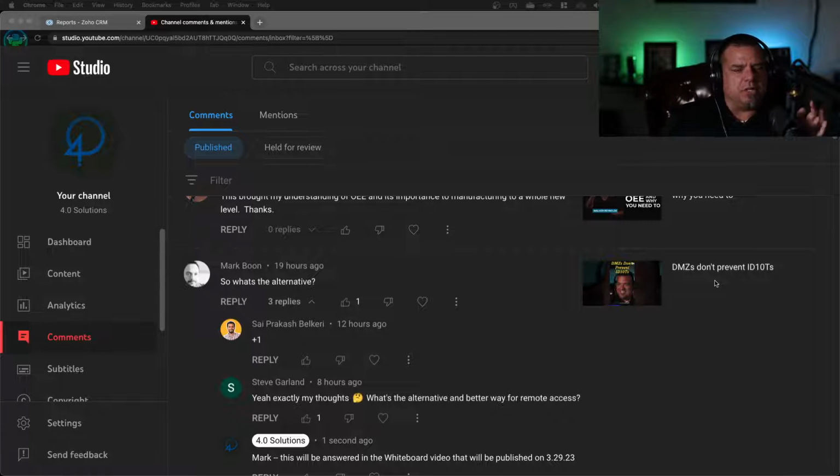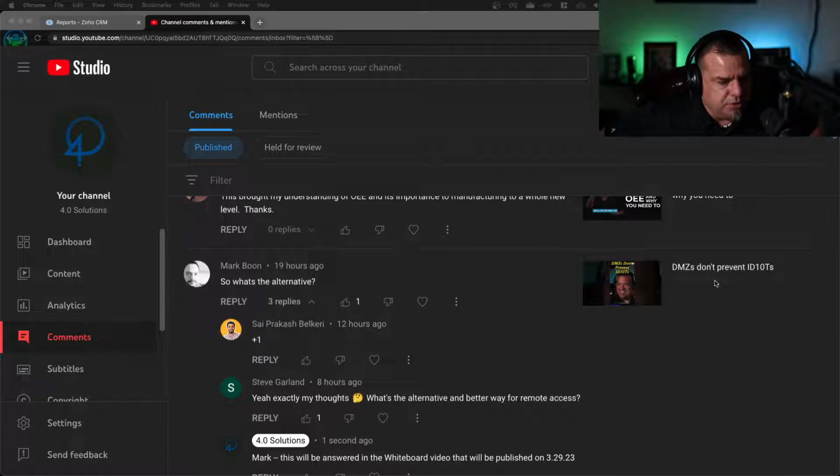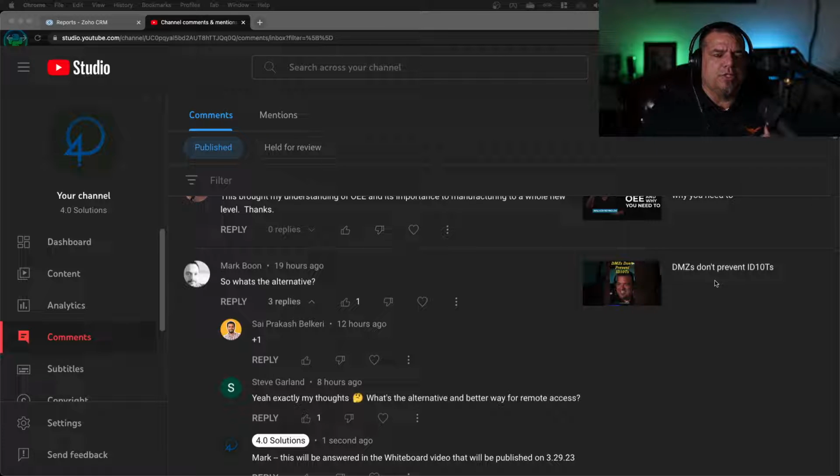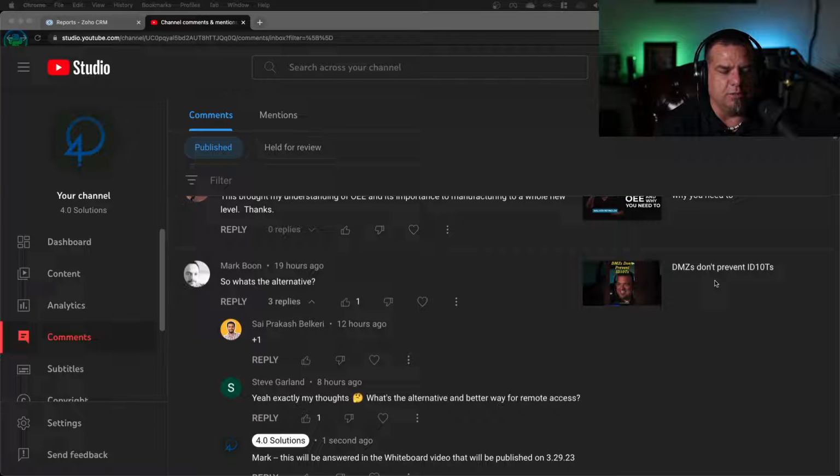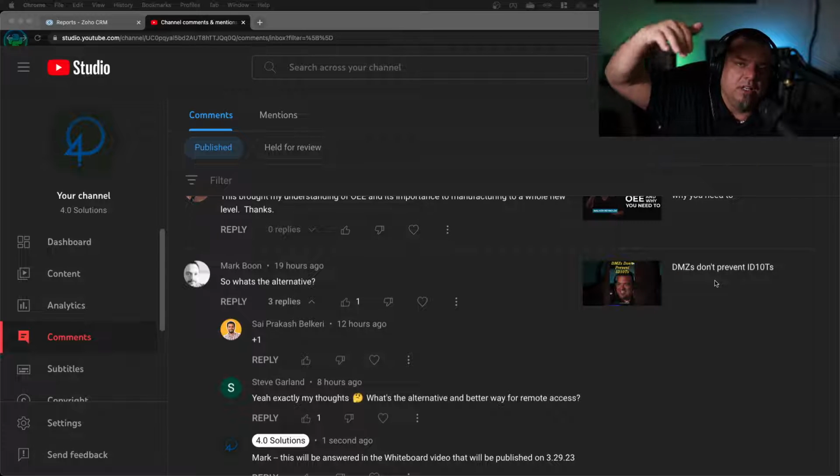For those of you who do systems integration and work with clients who use the Purdue security model and are familiar with DMZs, most of the time, let's say the future of work's remote. So you're a contractor, an integrator, an engineer, working remotely, and they need to get you access to the plant floor to access HMIs or a server on the plant floor, or to acquire data from PLCs, whatever it is. The way they generally do that is they'll put what's known as a jump server inside of the DMZ, something that has access from the external.